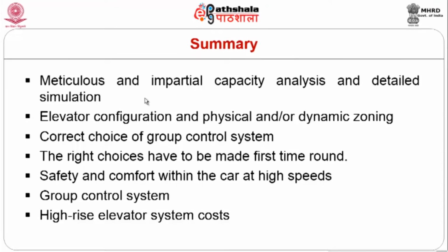If the planning and the simulation factors are independent, the results that we get may have implications on cost and wastage of materials and time at site. Therefore, meticulous preparation and planning are needed before getting into detailed simulation. Elevator configuration and physical and/or dynamic zoning is very important in terms of planning. Correct choice of group control system is also vital. The right choices have to be made first time round.